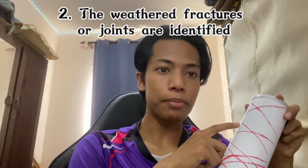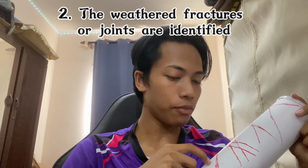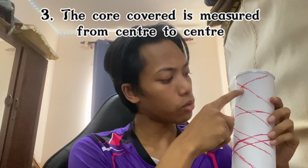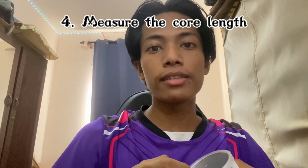As you can see, there are fractures on the samples, so the fractures need to be identified first. For the fractures, the core recovered is measured from center line to center line. Next, the core length is measured. For example, for the first fracture, the length is 90 mm. So the first data is 90 mm.